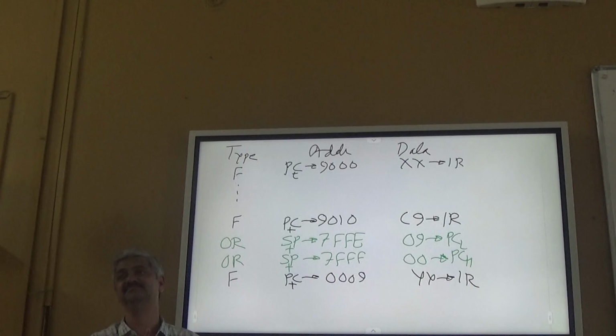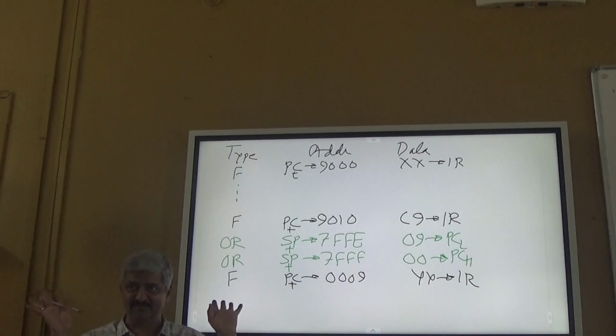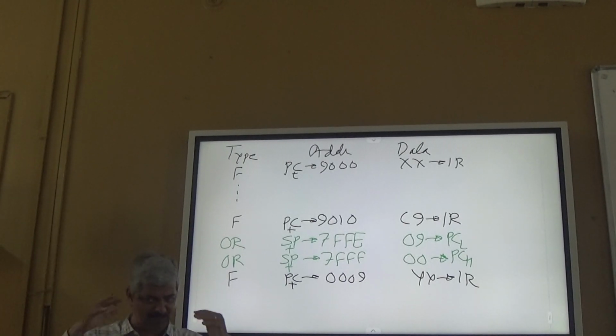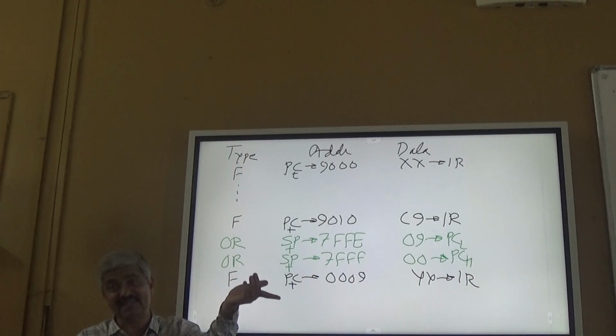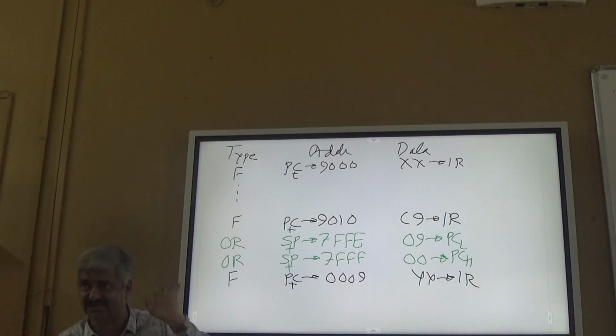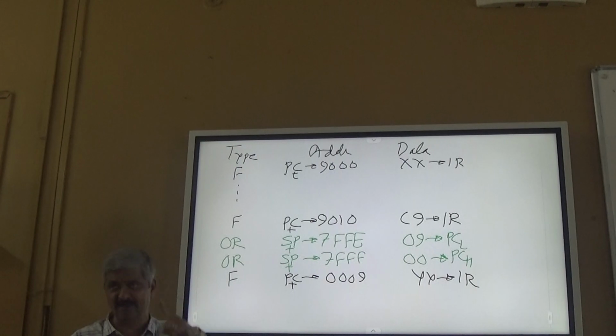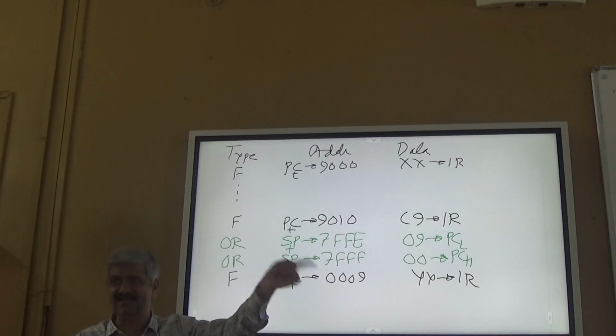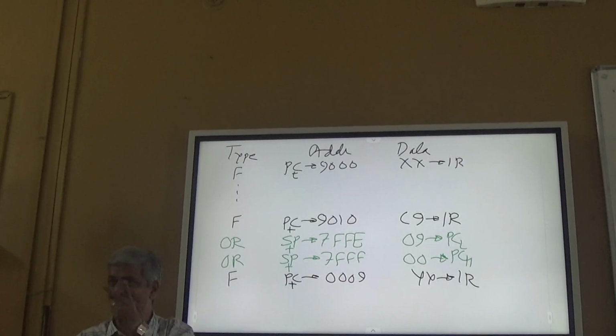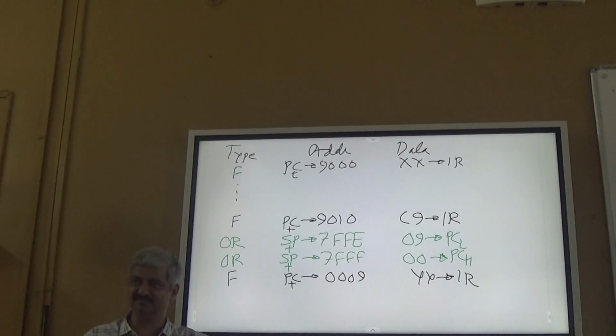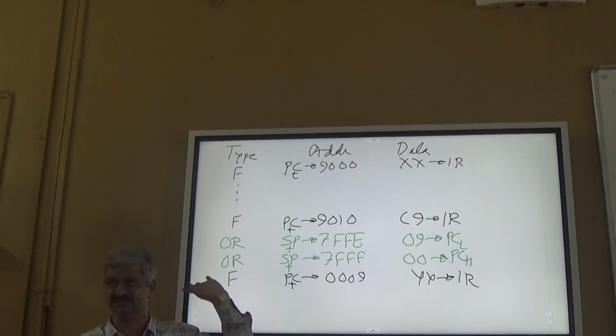Now what will we have to do? In the subroutine they should not be changed, but I want to use them. What is expected to be reflected in the result? Only HL. So HL is the source and HL is the destination. The subroutine is just like a mul instruction: multiply H and L, result back to HL. Only HL should be changed and all other registers should not be changed. But if that is the condition, then I can't write the subroutine because I want to use the registers.